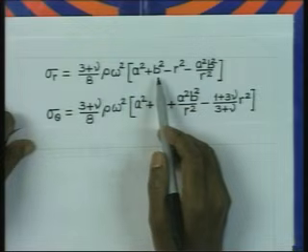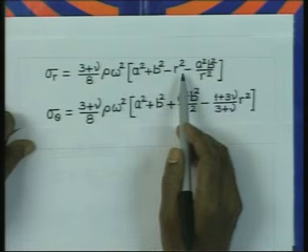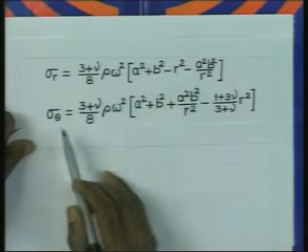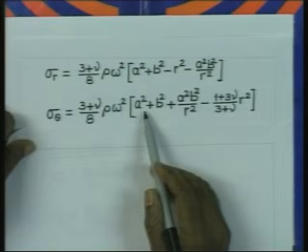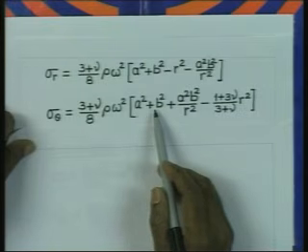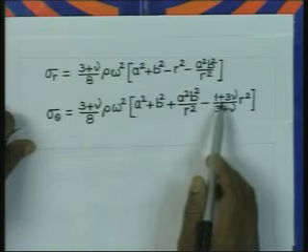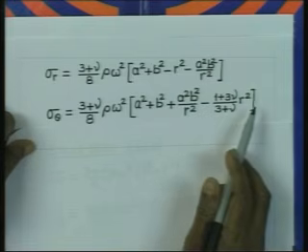Now, if the disc is solid, what we are saying is that a is 0. So, you can see this expression here, a is 0. So, we will be simply left with b square minus r square here, and if a is equal to 0 in this expression, then we are going to have b square minus (1 plus 3 nu) by (3 plus nu) r square.